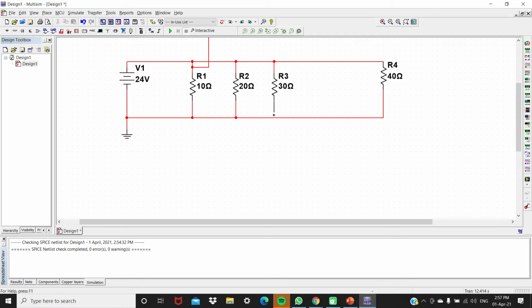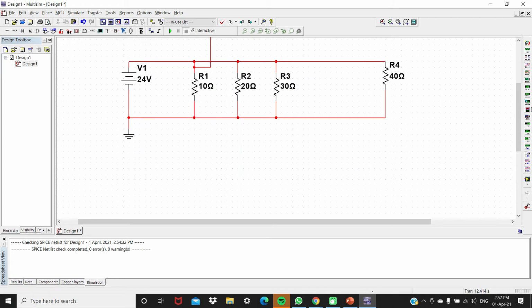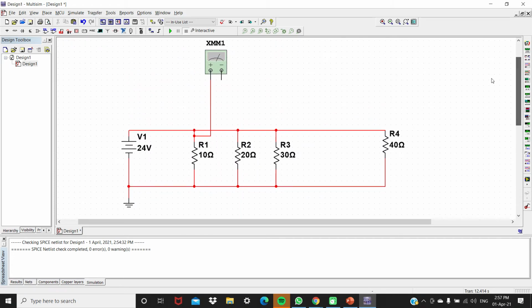Okay, the meter should be connected in series with the resistor that we want to look at the current. So the negative one should be where? It should be R1, in series, meaning it's not going to go across the resistor. It's going to be side to side with the probe, but you're going to remove the connection. Just put the connection of the probe beside the positive probe.